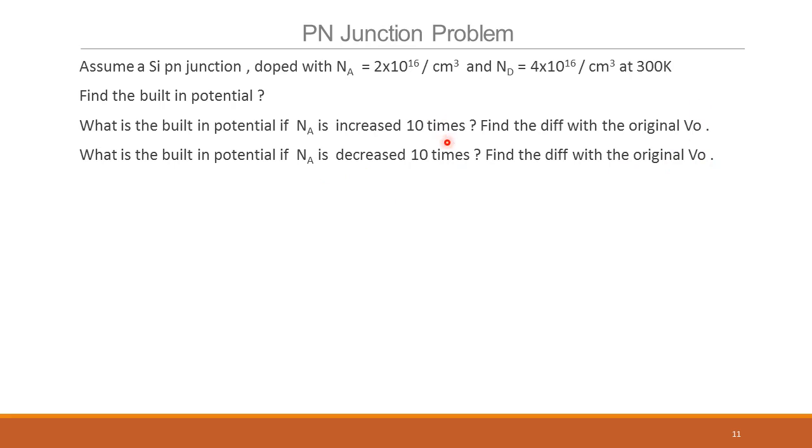This problem is given such that even though Na is increased or decreased 10 times, I want you to understand how sensitive the built-in potential is to Na. Because it's a log, you would expect it not to change 10 times. It should be much lower than that. You'll see that when you do the problem. Okay.